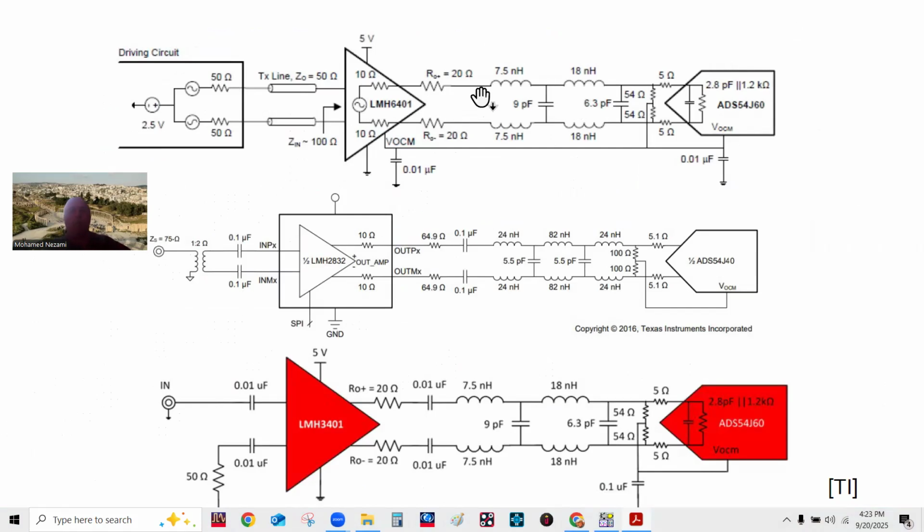I start seeing inductors, of course, because at these frequencies that you're driving the ADC, you're going to have to resort to either passive LC filters or ceramics or microstrip filters. Okay, so it's pretty simple. You come in single-ended, use a balun to create your input to the differential amplifier, and then equally on both sides of the rails you can drive your ADC.